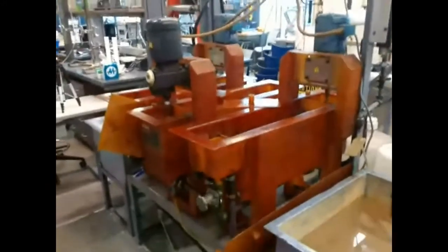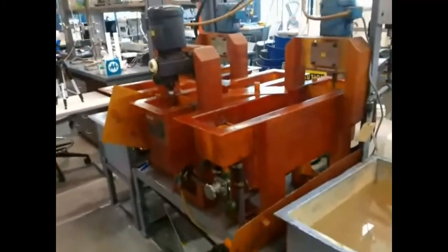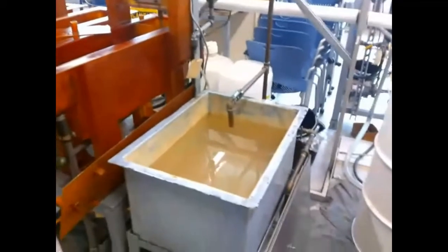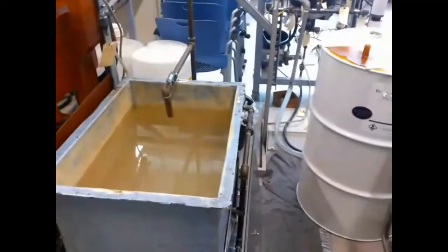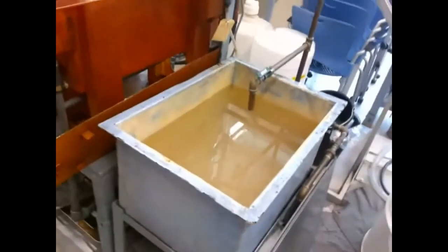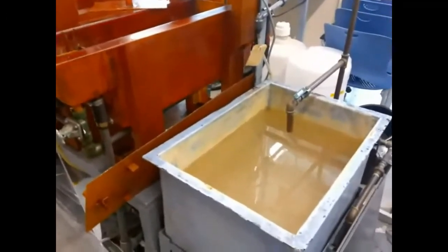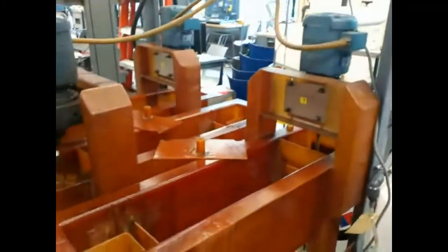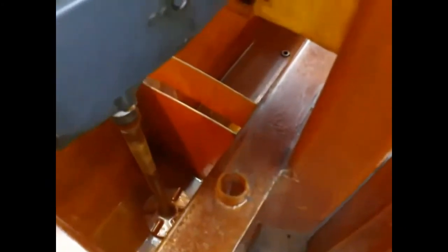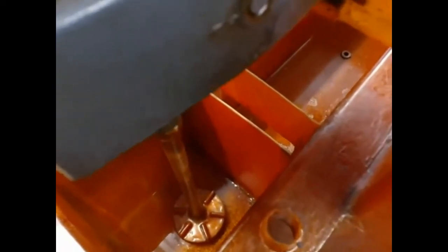And then finally, the last experiment that we have here is called a liquid extractor. This is another important chemical engineering process for removing some material from another liquid. In our case, we do a simulation of this. We have a large 25-gallon tank of baby oil, basically. It's called mineral oil. Here's our 55-gallon drum of the mineral oil. We contaminate it with vinegar, or acetic acid, and then we run it through this liquid extractor, where the water and oil go into these mixer areas where you can see the rotating impeller.